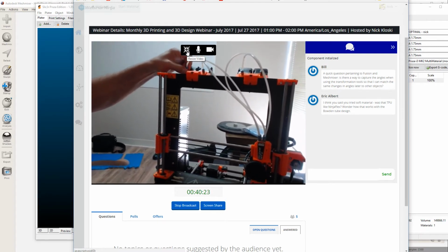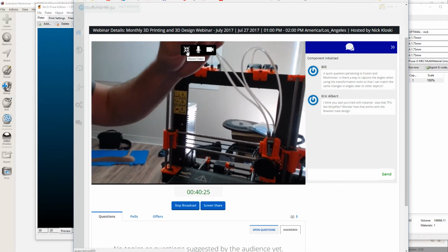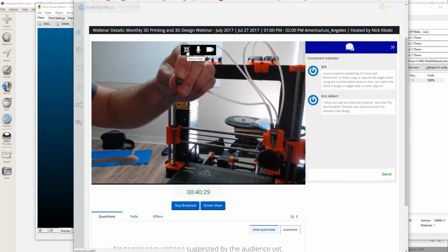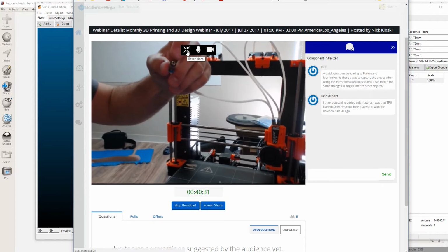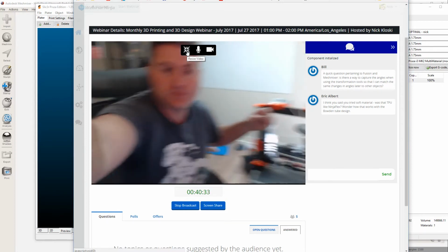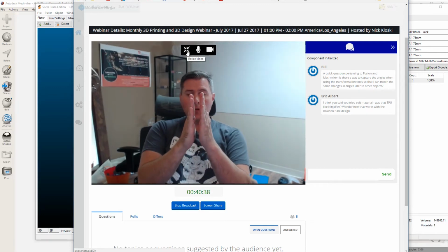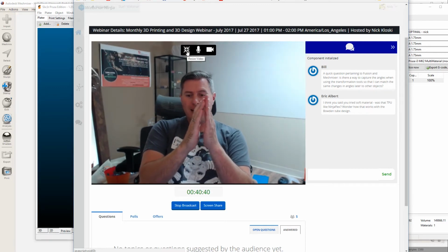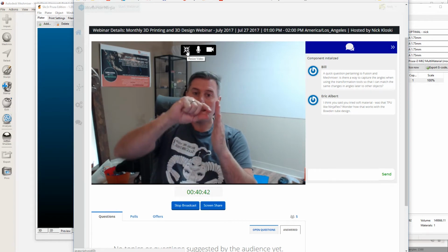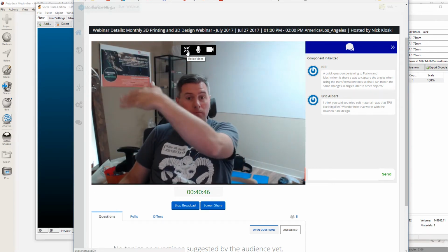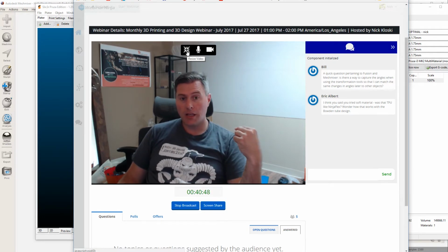Let me take this out. So there's a little tiny bit of space, a little bit of leeway. But that leeway, if you have a flexible filament, even a little bit of leeway can allow the filament to kind of bend inside. And that gets compounded over a long distance so that the filament has a lot of bend in it before it gets to the heating element.